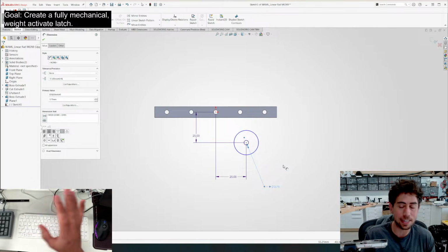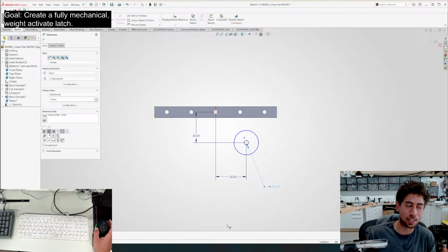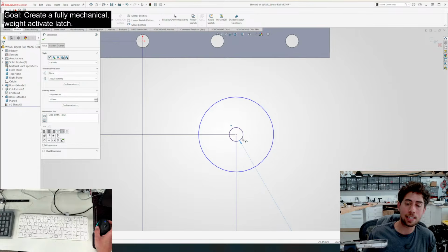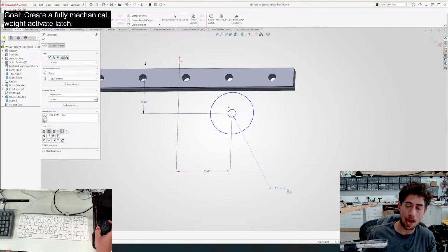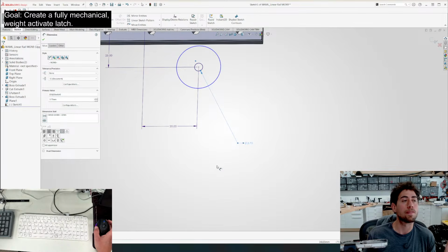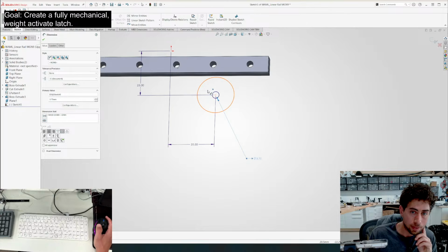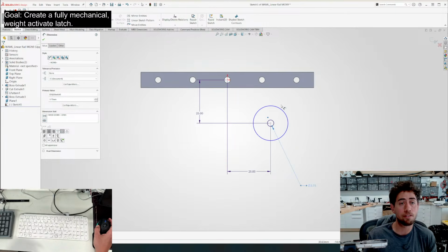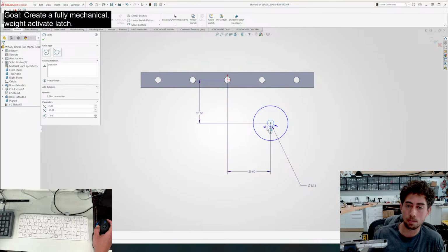As far as dimensions and tolerances go, when I'm threading directly into a 3D printed part with an M4 screw, I'm always gonna make the hole 3.75, and it comes out of the printer at like 3.5 or even 3.4, so smaller. So that's a rule of thumb. And if we keep doing these streams, you will see my rules of thumb are pretty consistent.